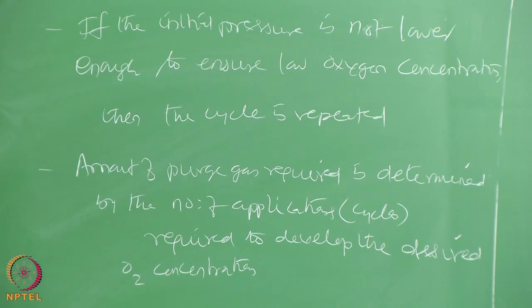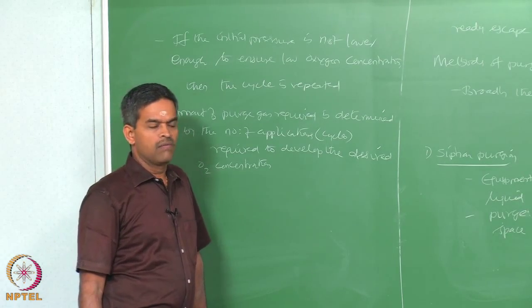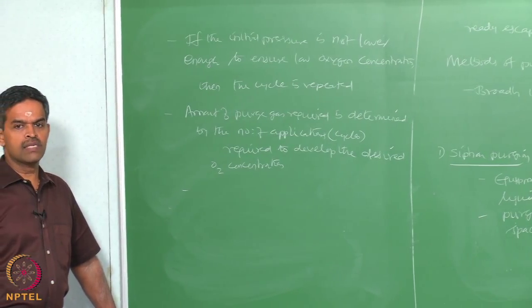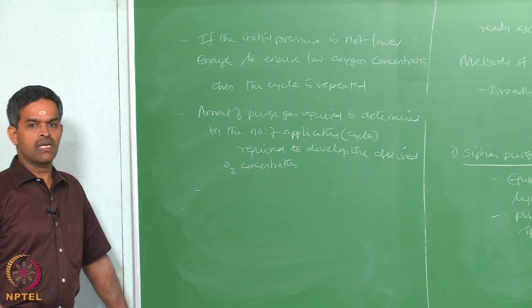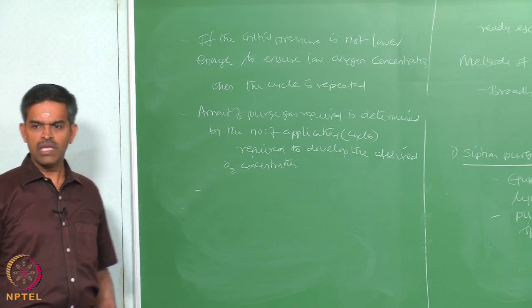If you are talking about purging in parallel two or more containers which are joined by a manifold, in that case purging is done as a group. Then the vapor content of each container should be checked for completeness of purging. Okay, that is very important.